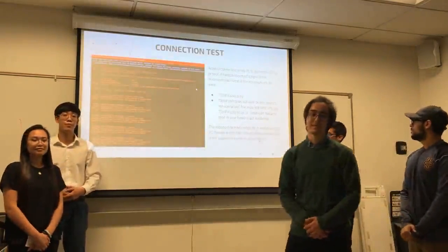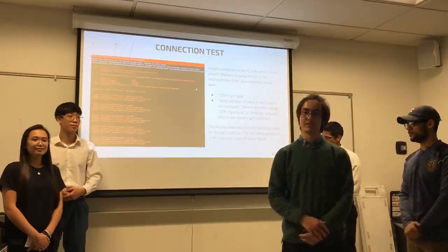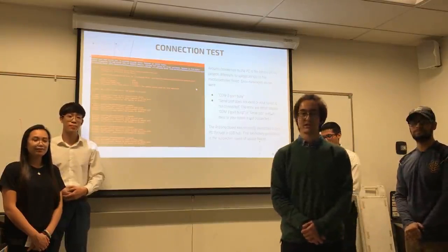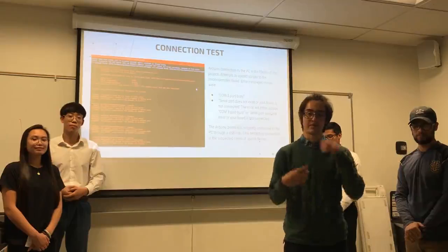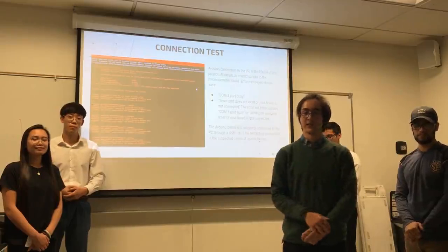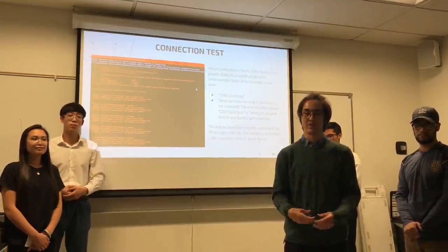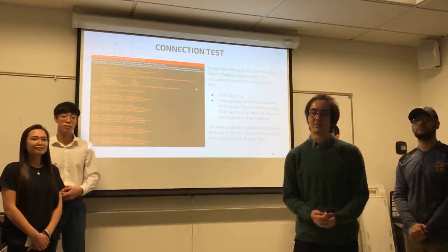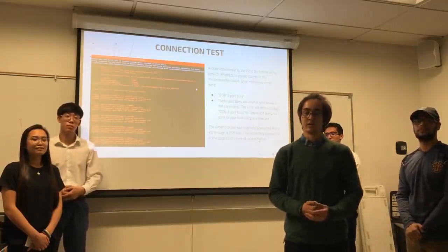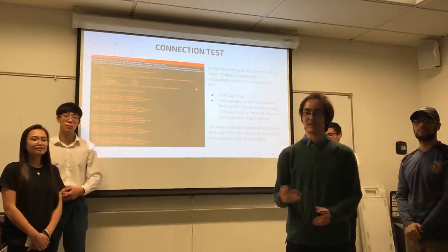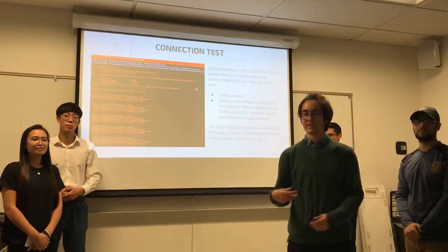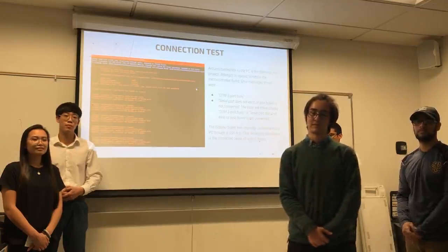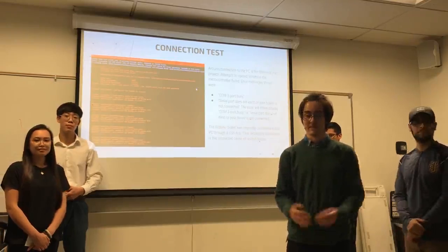One of the first things that the team started to work on was making sure that the connection between the Arduino and the computer was established. When we found the project in its state from previous teams, the Arduino, whenever code was uploaded to it, even simple codes like math, would just result in errors. It turns out that the Arduino was connected to a multi-USB port, which created a lot of interference in it, preventing codes from being uploaded properly. By connecting our Arduino directly to one of the computer's USB ports, we were able to solve this issue and codes would be able to be uploaded with no problem.